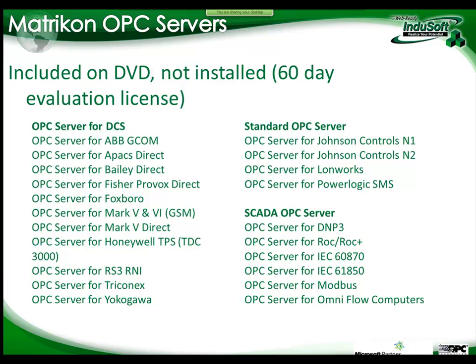Okay, and as part of the package, we can also offer you standard OPC servers for some specific protocols like LonWorks or BACnet, and some other OPC servers that we even have drivers for, but you may have more options with the OPC server if you want, right? From DNP3 or IEC 60870, we have the driver for the 104, but you may want to use OPC instead, so you can get that through Matrikon. Same thing about Modbus.